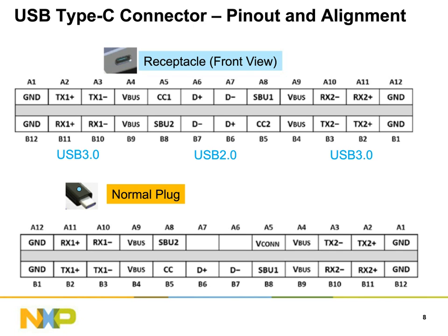And let's look at the pinout of the Type-C connector to see how this single connector allows you to do this. As you can see, it's a 28-pin connector, and right in the center you see your D+ D- lanes, which we all are familiar with from our USB 2.0 days. Those are the lanes dedicated for USB 2.0 traffic, and then in total you see 4 pairs of high-speed differential channels, 2 on each side, which are TX, RX differential 1 and 2.